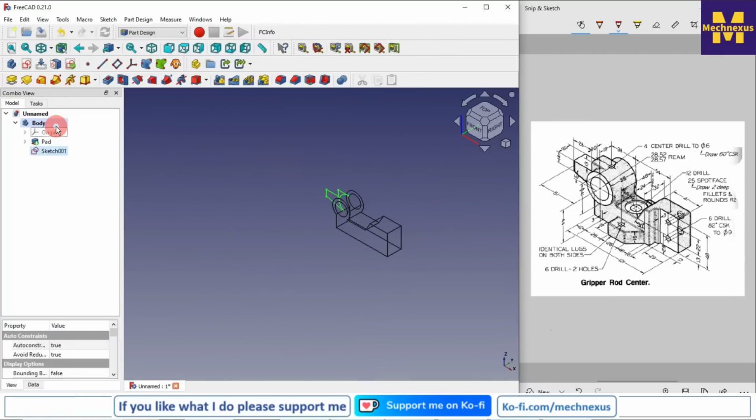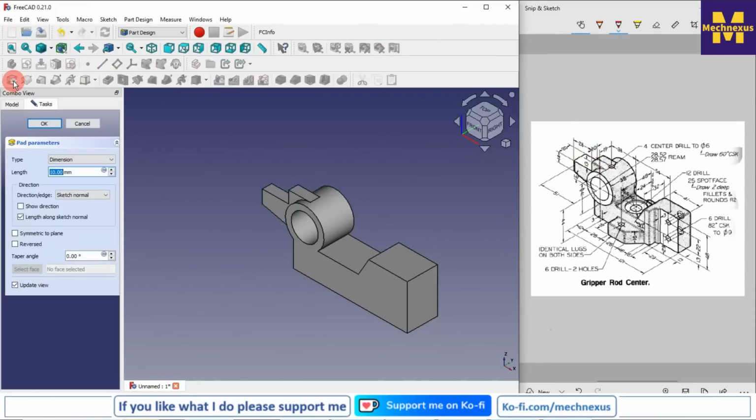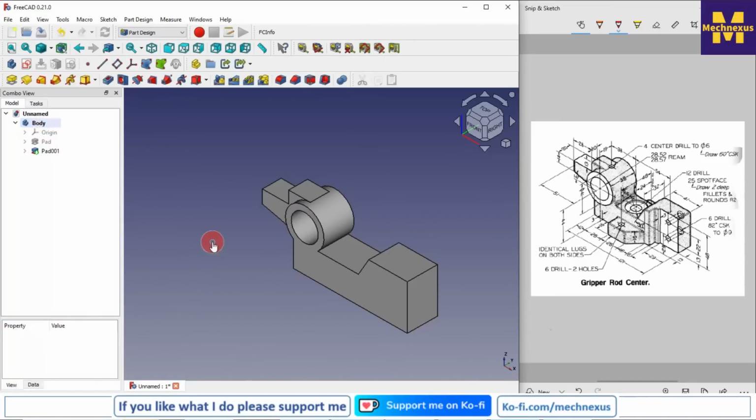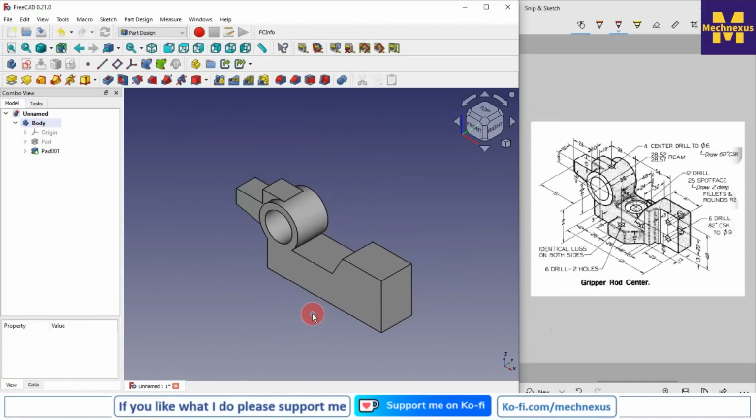We will come out of the sketch, and from here we will switch to the flat lines. Now if you see our profile, we have the extrusion length of 20 mm. So we will click on the pad and give the 20 mm dimension, and from here we will click on symmetric to the plane and say OK. Now we will move to the next feature and draw it.